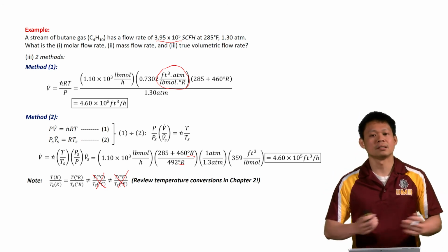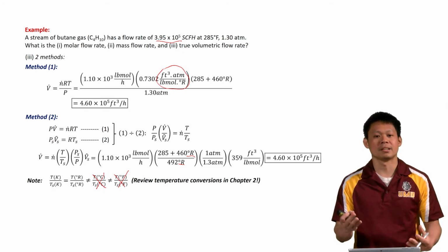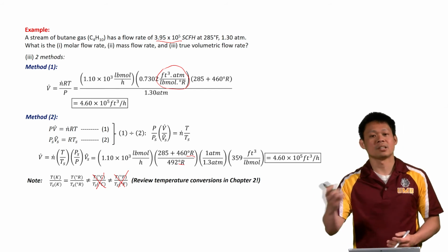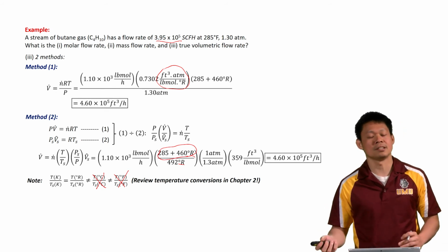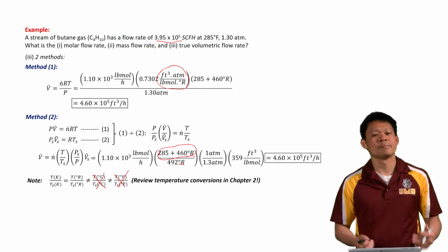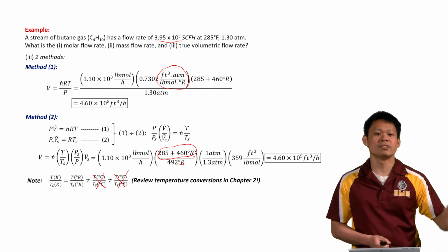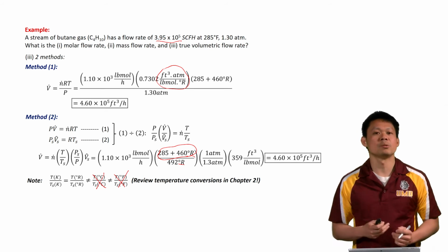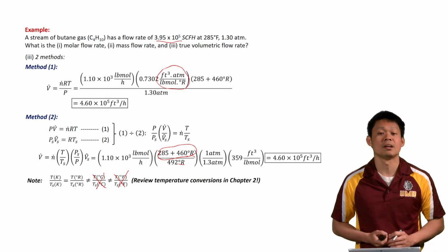Unlike most other quantities where we convert from one unit to the other by just multiplying by some factor, when we talk about temperature conversions, you have to add some constants in some cases. Just for example, converting from Fahrenheit to Rankine, you actually add 460 degrees. And because of that, the ratios are not going to be the same. So you can take the ratio in Kelvin, ratio in Rankine, but not in Celsius or Fahrenheit. So as you're doing this ratio method, be sure to keep in mind that you cannot do the ratios in Celsius or Fahrenheit.